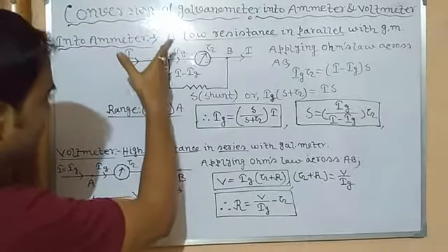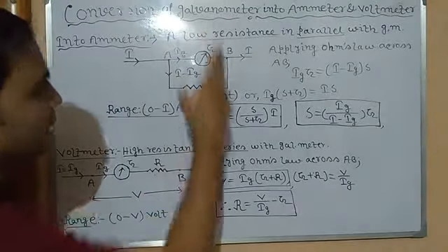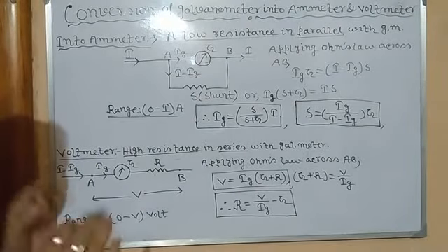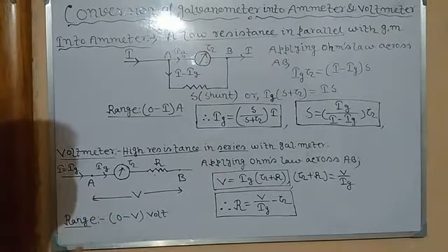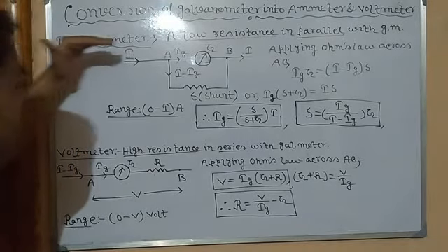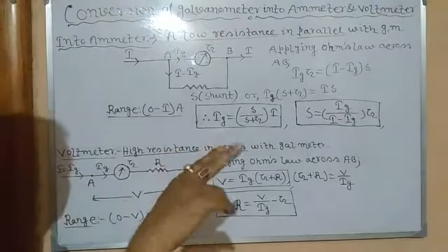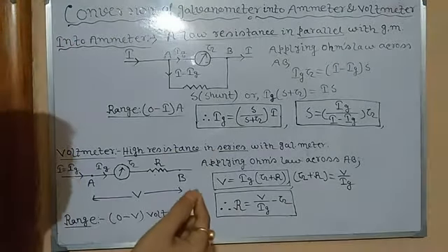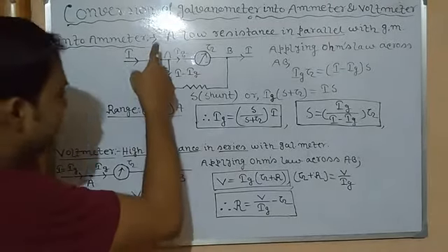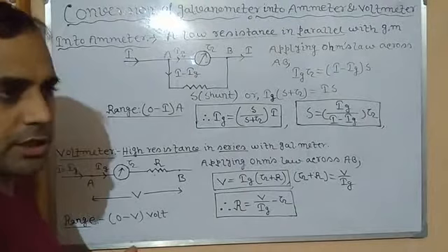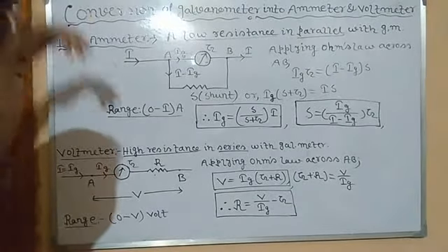It takes an alternative way through a bypass and reaches its destination. Through an example everything becomes easier. In the same way, only a small current is enough to deflect the needle of the galvanometer. So a shunt is an alternative path through which a major portion of the current can pass.